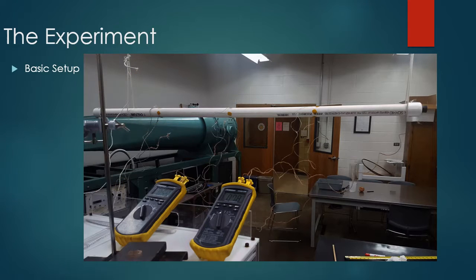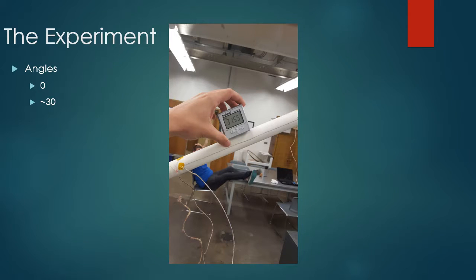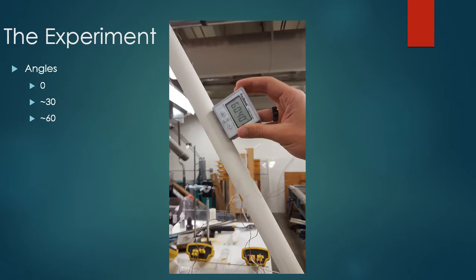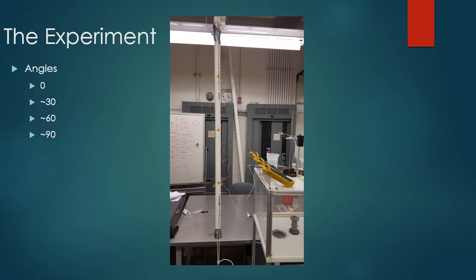Water and ice were added here. A thermocouple was also placed in the hole to measure the water's temperature, and a rubber stopper was inserted. The angles we took measurements at were 0 degrees, 30 degrees, 60 degrees, and 90 degrees, or vertical. Each angle was verified with the angle gauge that was seen in the previous slide. At each angle, we waited until steady state was achieved and then recorded the temperatures.